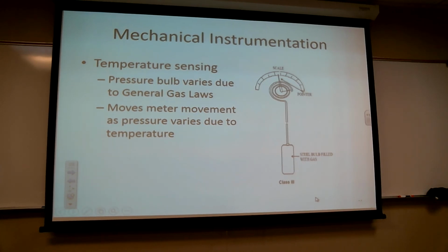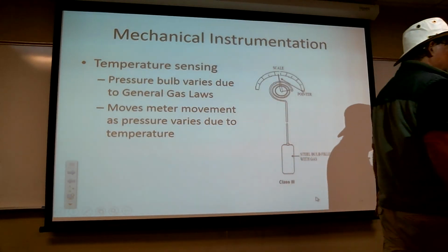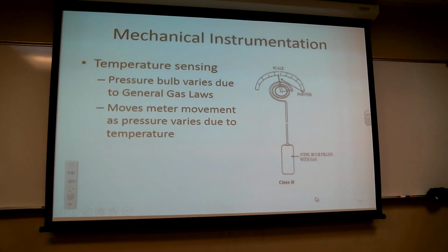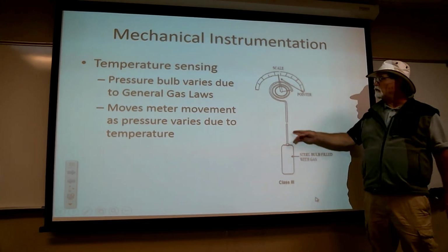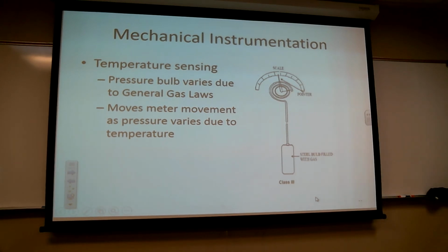Temperature sensing, still pretty commonly used these days. We have what's called a temperature bulb, and they made so many of these that they actually came up with SAE standards for these. There's a standard SAE fitting that goes in around the bulb shape, and the bulb will come with this big long tube completely soldered all the way up to the gauge. They're all together as one piece.